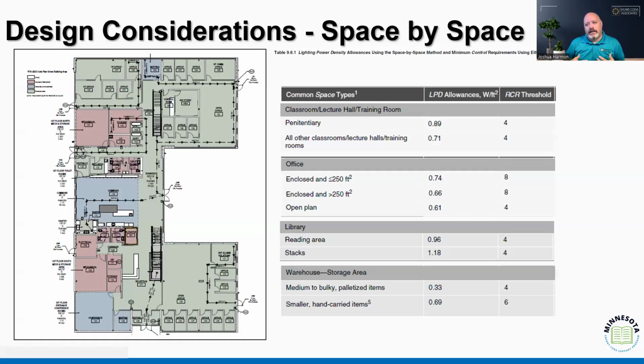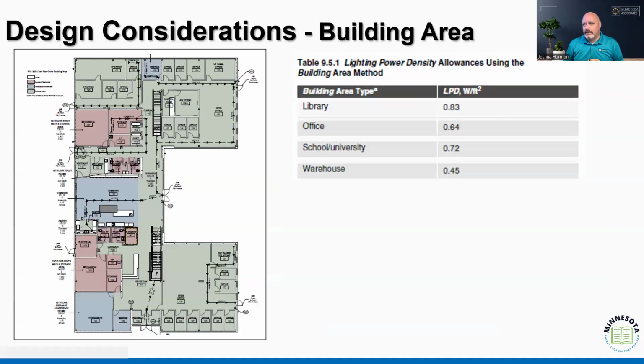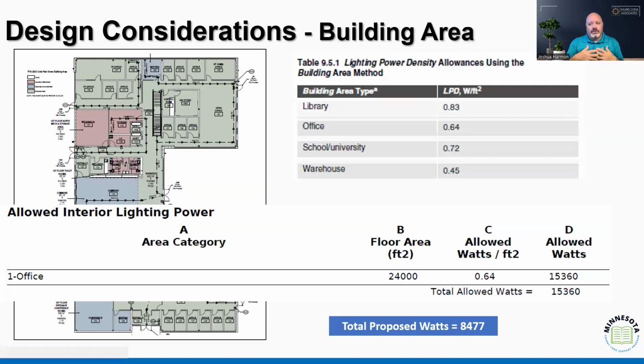here, when they did their calculation for this facility, there was a disconnect between what the comm check said for the number of lights. I don't know if I have that comm check in there. Right? So the number of fixtures that they listed was about 115. And the actual number on the schedule that was on the electrical plan showed 254.